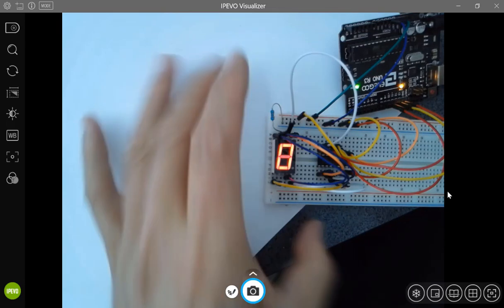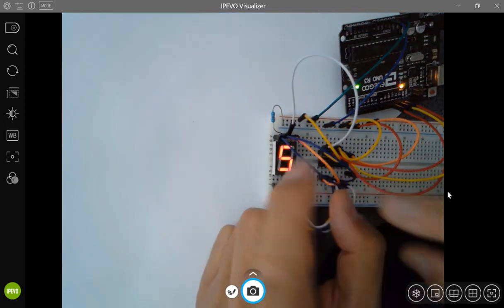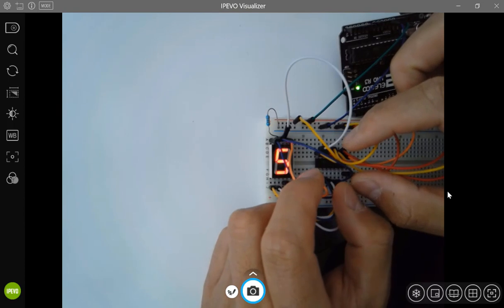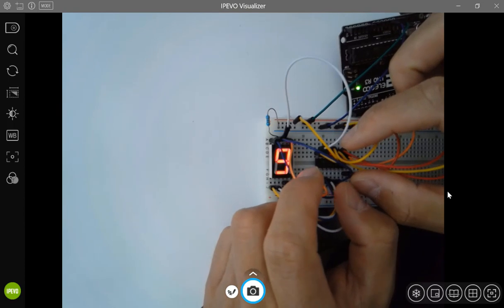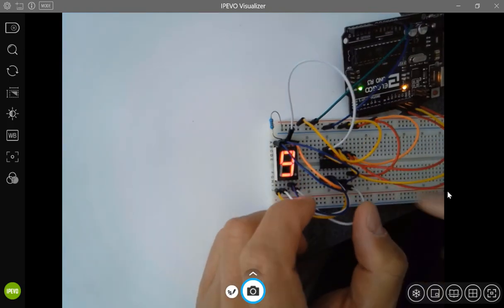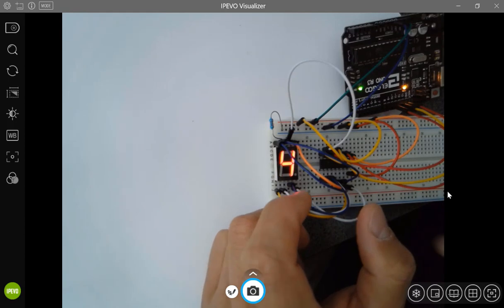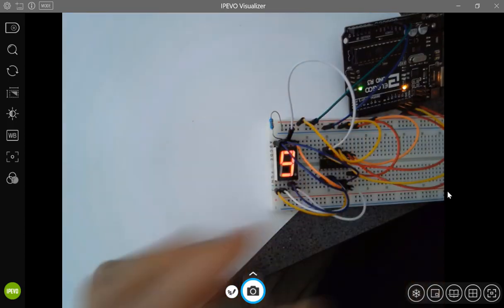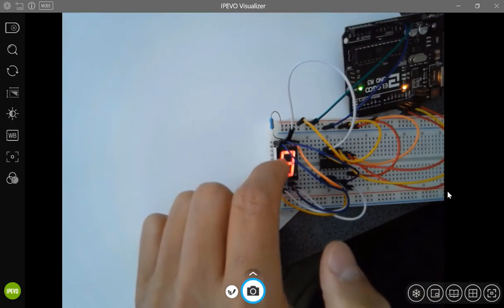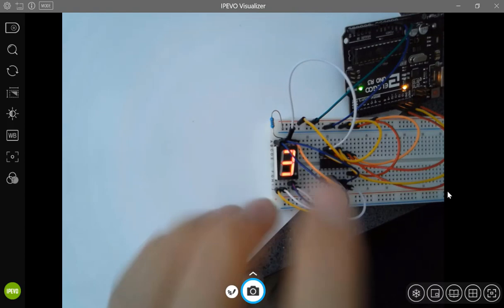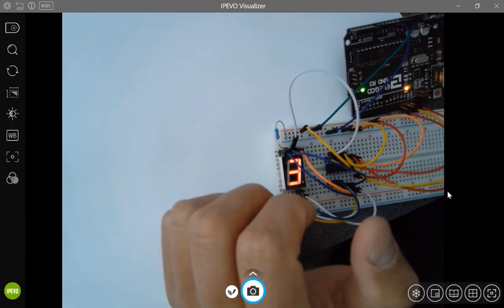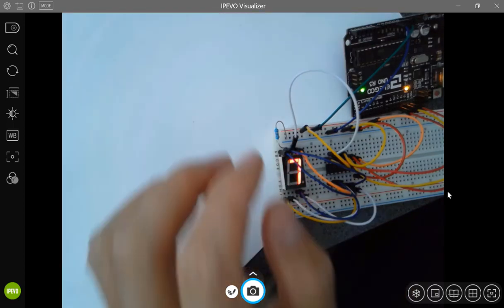Okay, and you need a shift register. Do you still remember shift register from logic? You probably forgot everything already. The shift register is this little IC device, and we're going to use it to shift every bit to the output, doing serial in, parallel out, to display a number here at one time. That's how it works. I'm going to explain more.